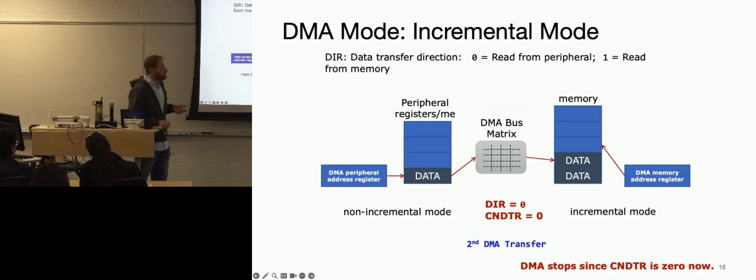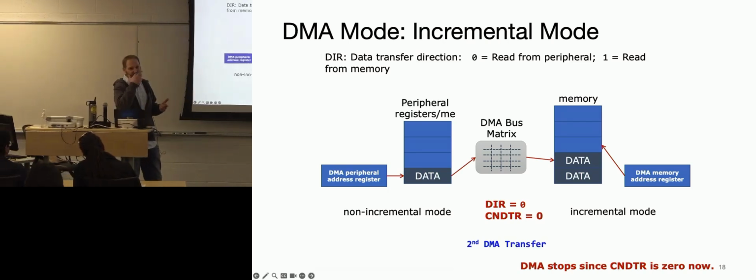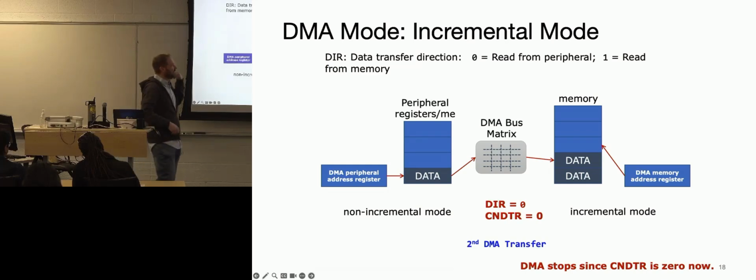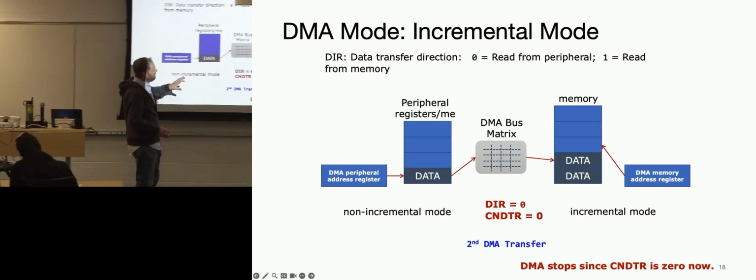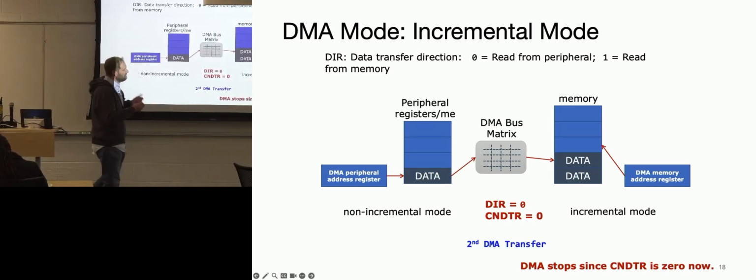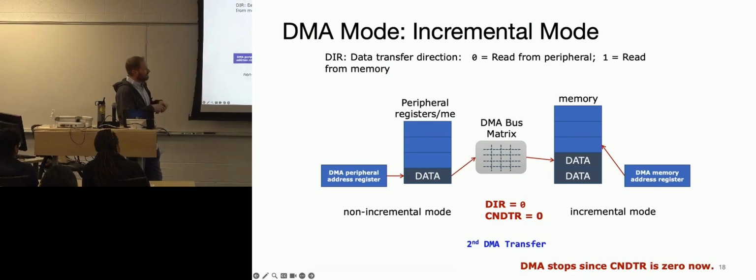The slides are kind of messed up. So this is an example of what would be good for a ping pong buffer. You can set up 2 of these. You can be filling up one ping pong buffer, then ping pong will go off and set up an interrupt that will tell your core, hey, start pulling data out of this other one. So a lot of these structures are really good for streaming data. That's primarily what they're good for.